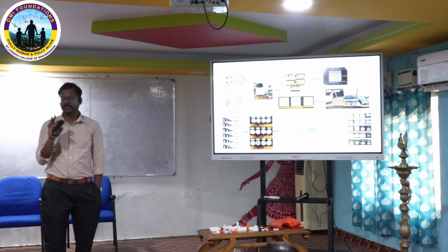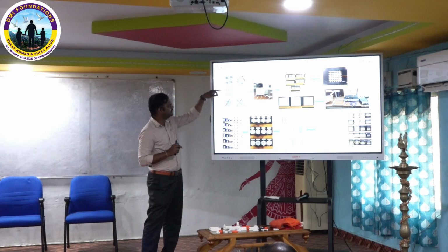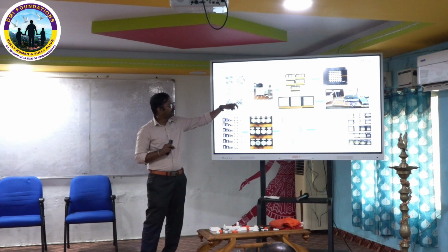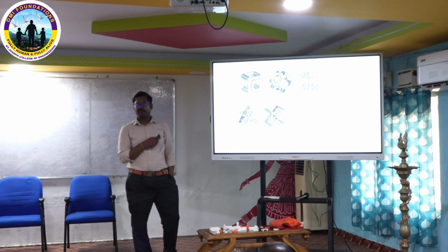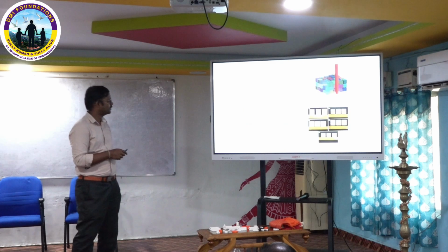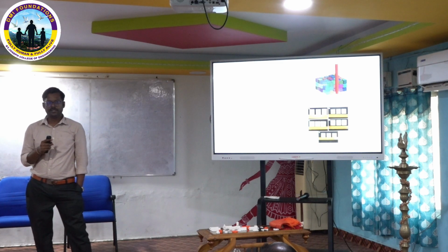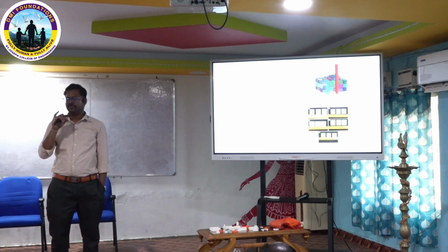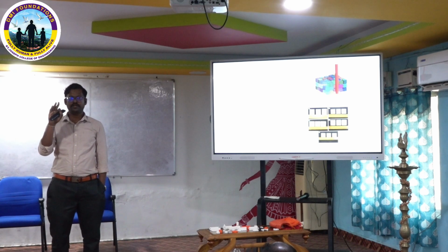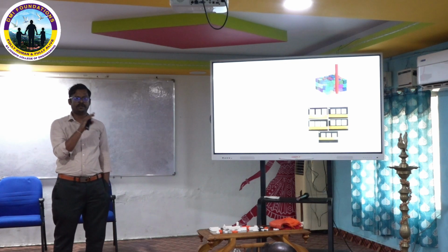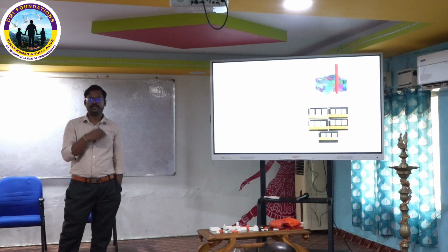For my PhD work, I selected 5 different unit cells, which have different topologies. In that, 3 are bending dominated structures, 2 are stretch dominated structures. So I fabricated with 10, 20 and 30 relative density and tested. I will show you. These are the 5 different unit cells I selected for my research. Then 3 levels I take. Why? Because I take another parameter as strain rate. Why? Because there are governing factors for a lattice structure. First one is relative density, then unit cell type, then what material we are going to use. Fourth one is what load is going to act on that, how fast, that means quasi-static or impact condition. Based on that, the property of lattice structures will increase or decrease.